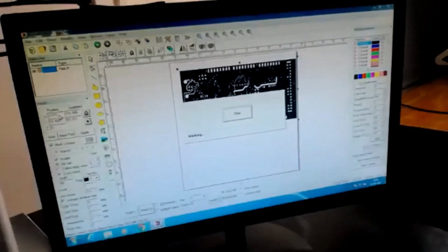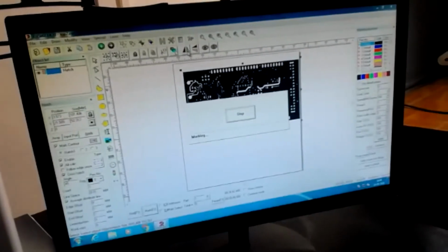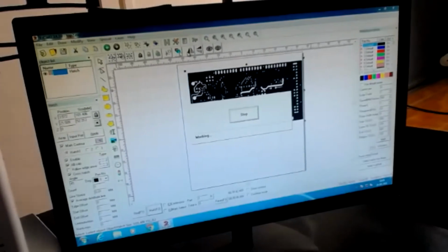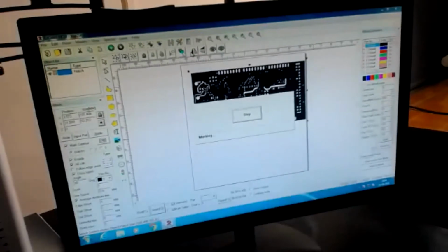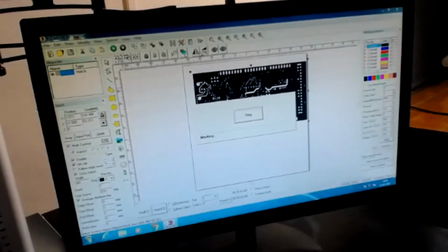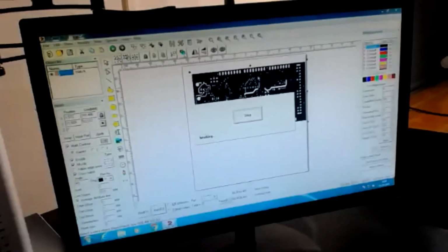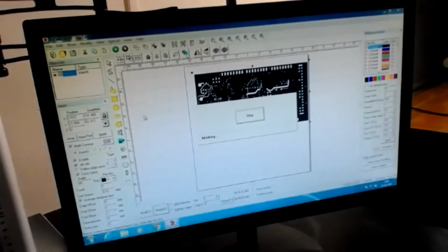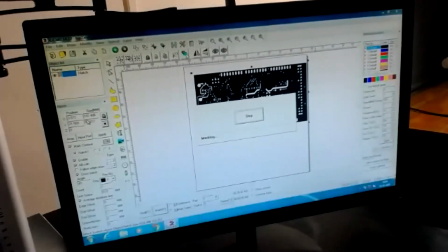For example, if you do the same calibration measurement on the top side, then for the bottom side you have to do a shifting, because when you rotate the board to the back side, what really happens is the left side will print on the right side. So make sure that you rotate the board 90 degrees and tilt this design 180 degrees, so that the desired part will be coming to the left side. Again, this position you don't change, you always keep it as 0, 0 and the desired value. So whenever you do this, the particular alignment will come to the desired point. So the process will get done.